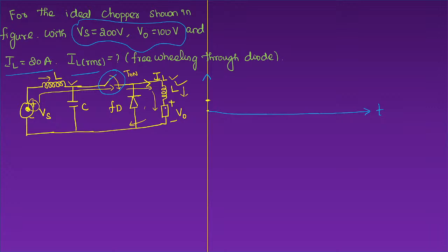Under this situation, if you observe this freewheeling diode, this is the anode terminal, this is the cathode terminal. If you focus carefully, the supply voltage has positive and negative polarity like this, and it is directly connected with the diode in this manner. Here the negative polarity will get reflected across the anode, and positive polarity across the cathode. Since this diode will be behaving as an off circuit, it is simply behaving as an open circuit.